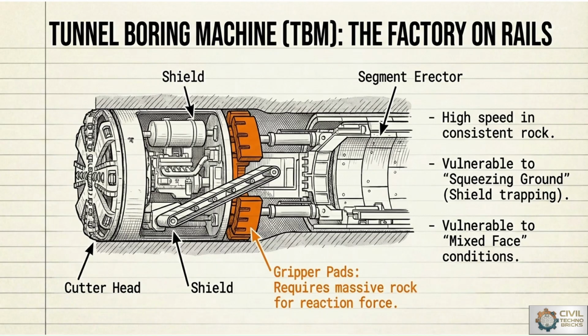The tunnel excavation method depends on geology, tunnel size, and project requirements, whether the tunnel is for transportation, water or hydrological purpose, or utility purpose. The drill and blast method is suitable for hard rock conditions, and tunnel boring machines are effective in uniform and stable geological formations. Soft ground tunneling requires special support and ground improvement techniques, where proper excavation methods reduce vibrations, instability, and construction risk also.